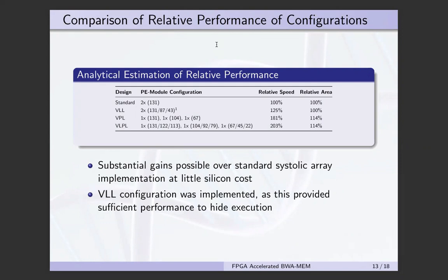However, for our implementation, it was sufficient for us to use the variable logical length systolic array, since it was enough to fully parallelize the FPGA execution with the CPU execution of the other functions. And also, it does not require any extra hardware.